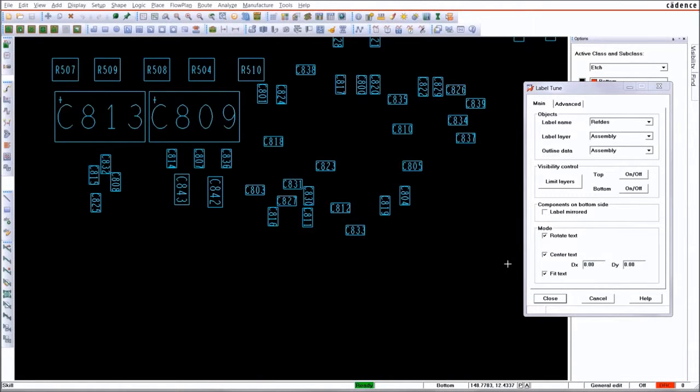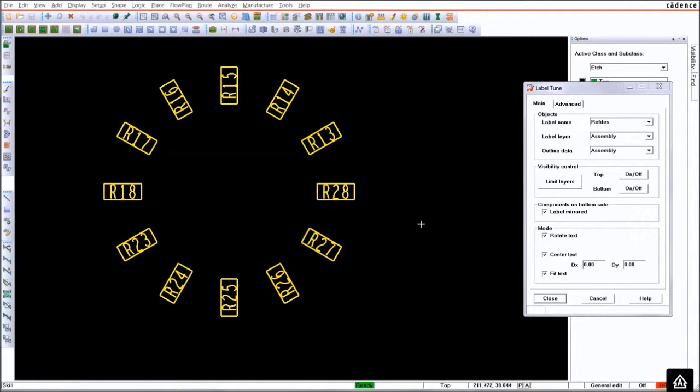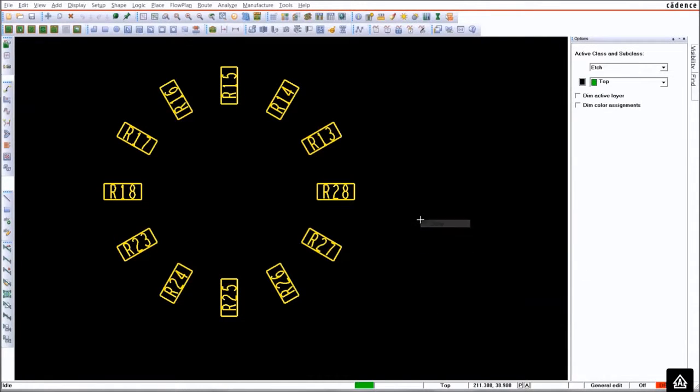And if you wish to mirror all text elements to the bottom layer, you can achieve it in the same fast way. It also works for rotated parts, so they become readable in a smart way according to technical drawing standard.